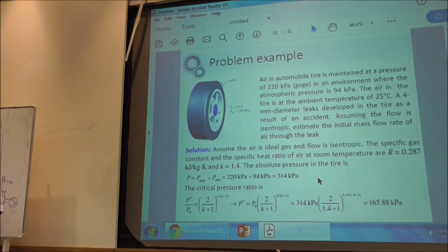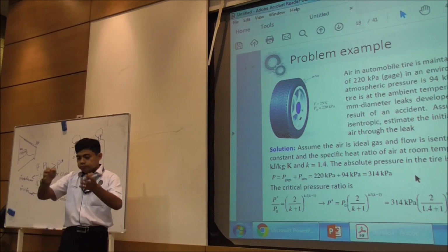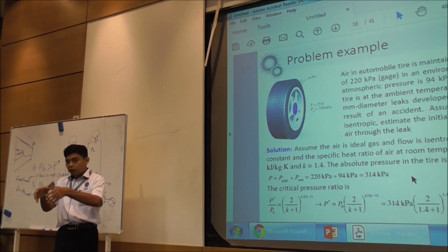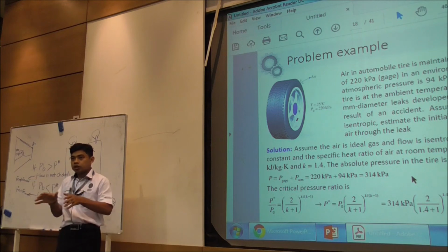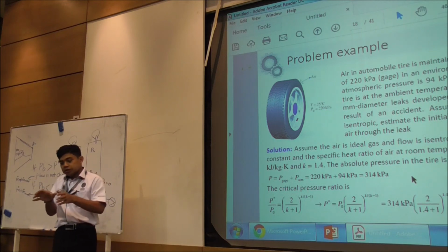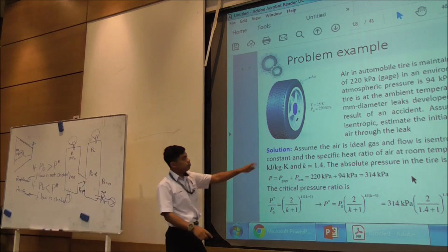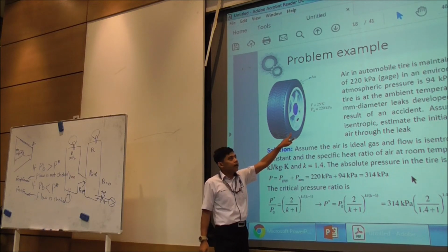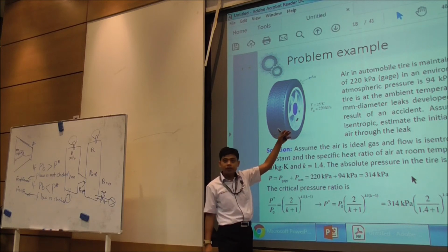When it is hot, it is liquid. When it is cold, it becomes solid, and it blocks the pipe. So how to release that is you release the pressure. By releasing the pressure, you make it melt. So how to do that is you put discharge equipment. You puncture it and then you release the gas.